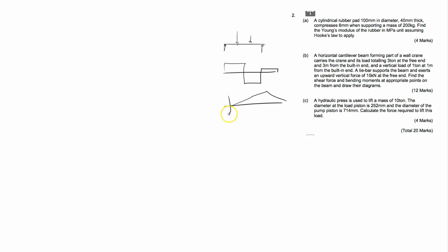And it's relatively straightforward. Cantilever beams are a little different. I'm just going to do a very, very rough sketch to show you the method we're going to look at this. So when doing a cantilever beam, I'm going to recommend that you draw from the right hand side. That's the wall end, or the built-in end as they call it. We'll have a beam extending outwards. It's 3 meters in length. It's got a ton at 1 meter.